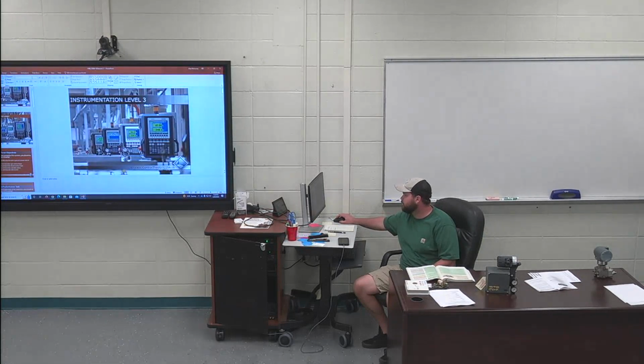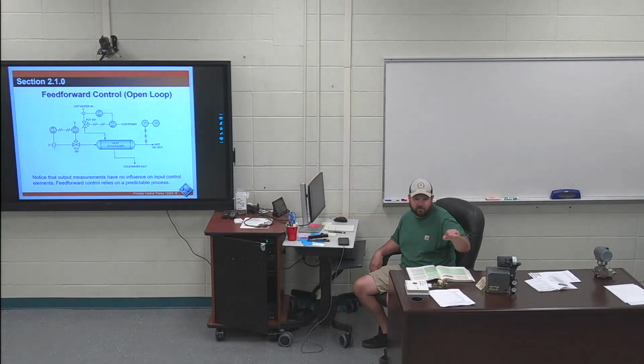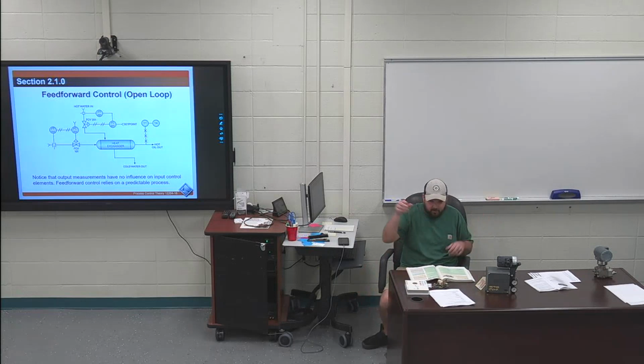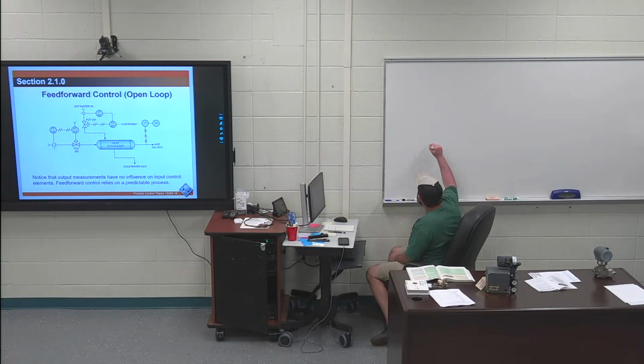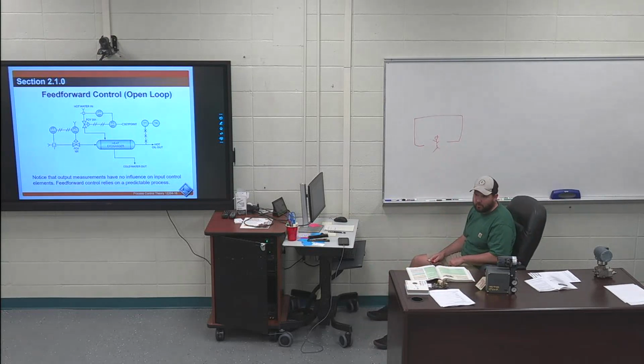Josh, you remember doing the open loop tuning all the way at the beginning of the lab? Remember opening up that valve a little bit and trying to get the output set just right to where it would keep up with condensed water? That's called open loop tuning. That's looking at where the level is, making an adjustment, going back and looking. You are acting as the controller. If you are acting as a controller, it's an open loop. Think of your loop like this, and then you're right there. It's not closed. There's no type of control or anything like that.